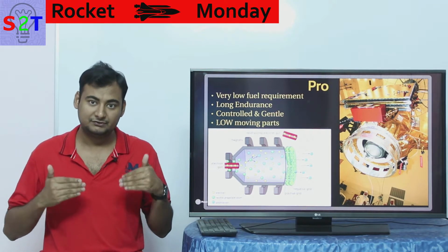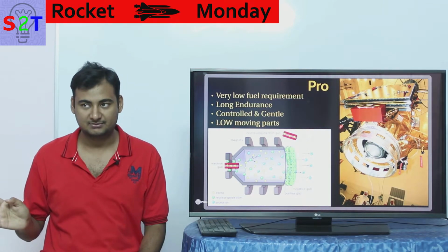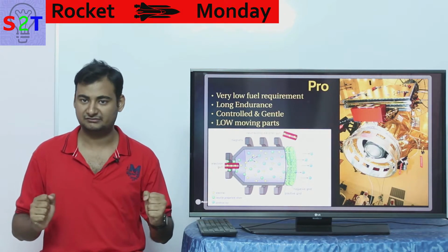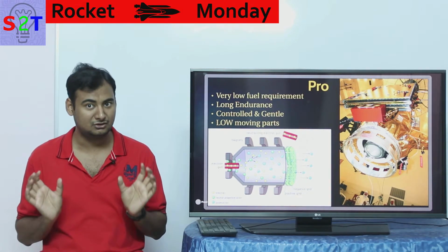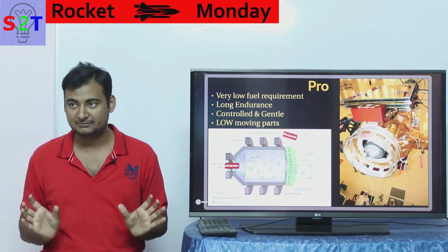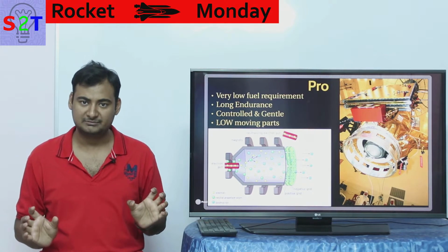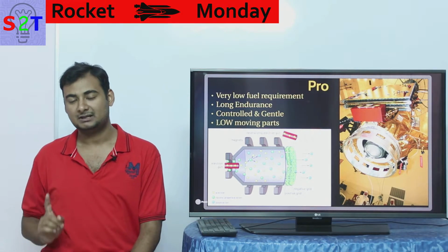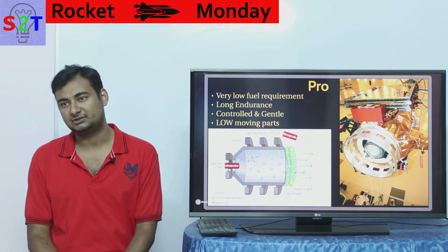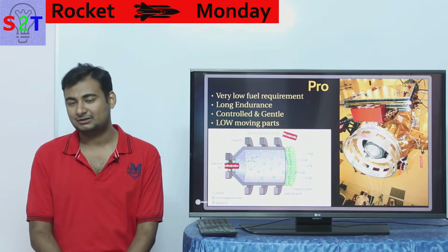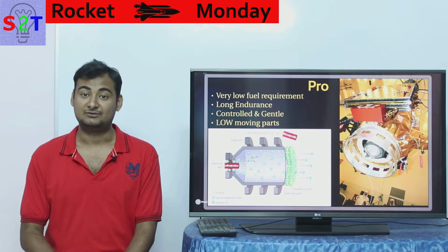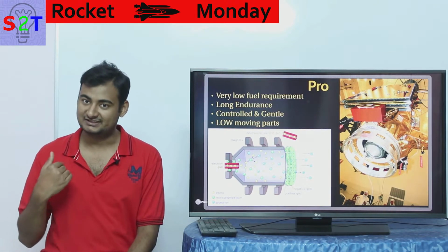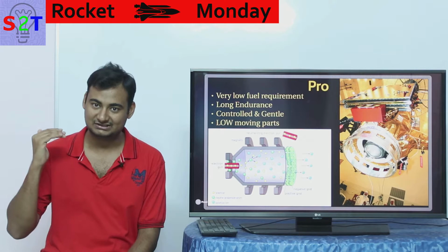Now, if you are going to the moon, don't even consider an ion engine. If you're going to Mars, the rocket engine is going to start very fast. Let's say I'm talking from orbit, not from Earth, so you both have the same orbital velocity. Now, if you start the ion engine, in the first week you will have very slow speed. In the second week, you have a bit more. In the third week, still more. At 1 month, you are now matching the speed that a chemical engine has. At 2 months, you are still accelerating. At 3 months, you are still accelerating.